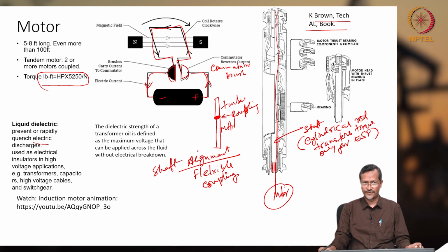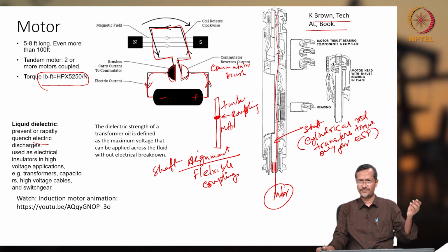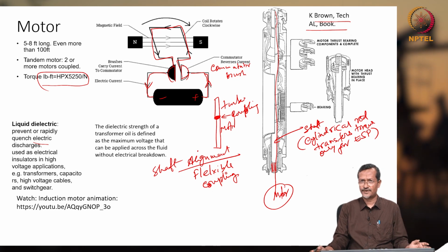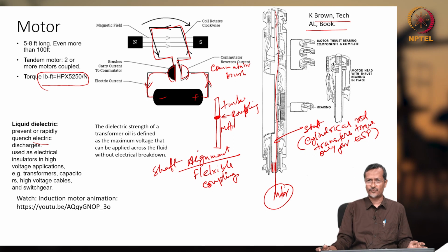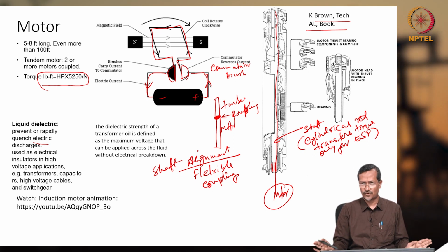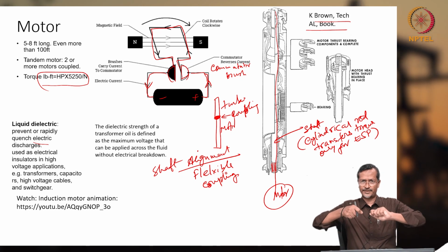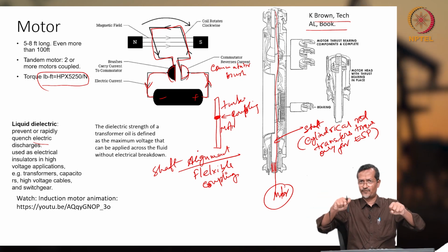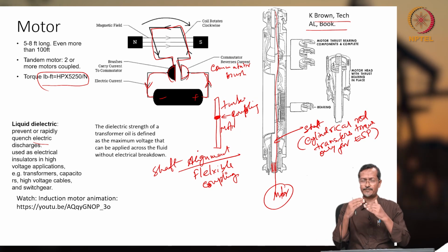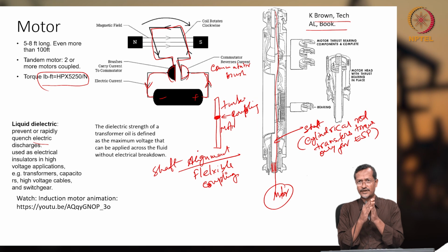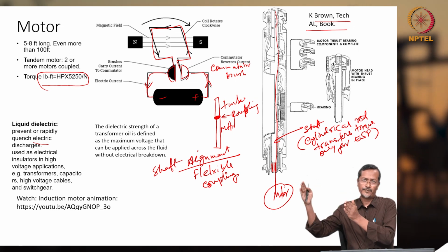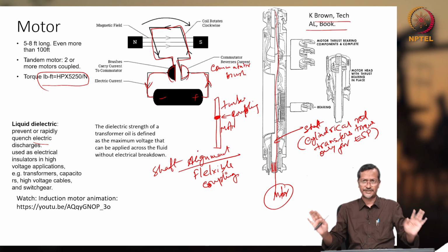If you see surface shafts, let us say shafts used for marine machinery or aircraft, they can transfer some bending moment and other forces also will be there. For your ESP system, the shaft will have only torque. Torque means shear force will be there, no tensile force or compressive force. Okay. If tensile or compressive force is there, then you have to make a proper mechanism so that those forces should not get transferred from one shaft or one component to another, say motor to pump or pump to motor.